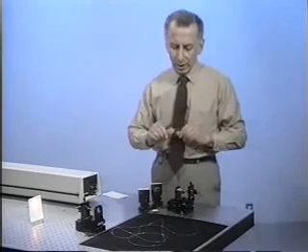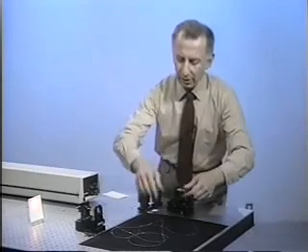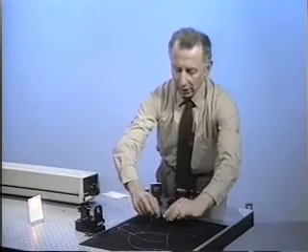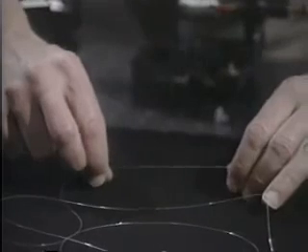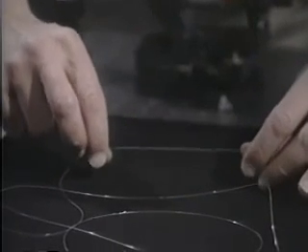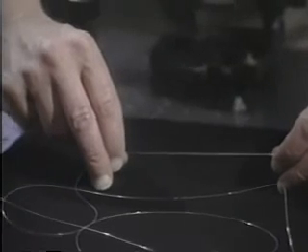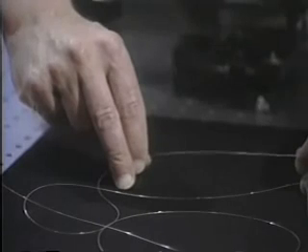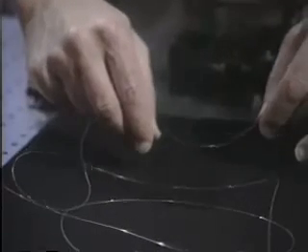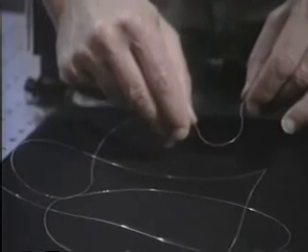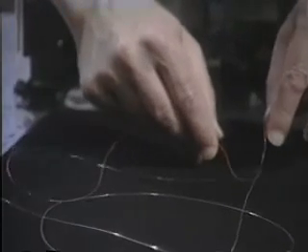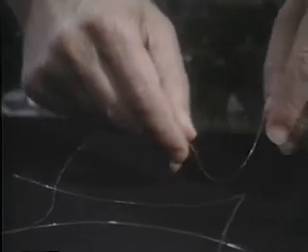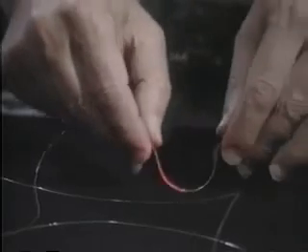Now I would like to illustrate some interesting phenomena about fibers. So if we get the camera to look over here, I want to illustrate how touchy is the propagation of light in a single mode fiber. Now here's a piece of fiber, and you can see that there's no light scattered from the fiber. Now all I have to do is bend the fiber, and you're beginning to see the light that gets transmitted out of the fiber, gets essentially kicked out of the fiber, because of the bend.